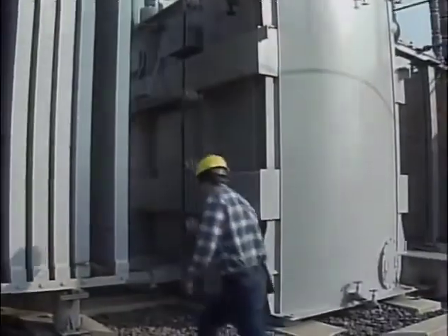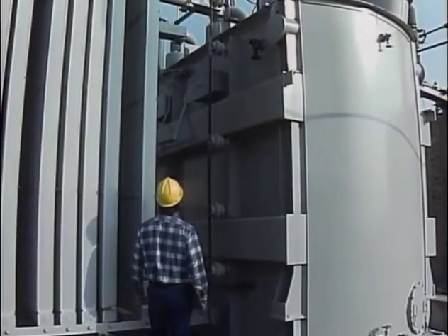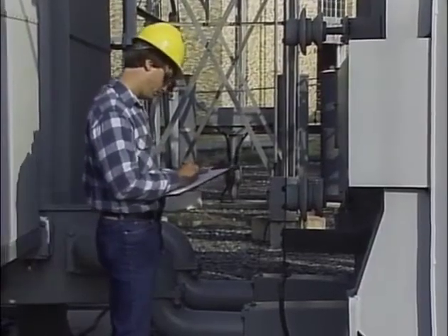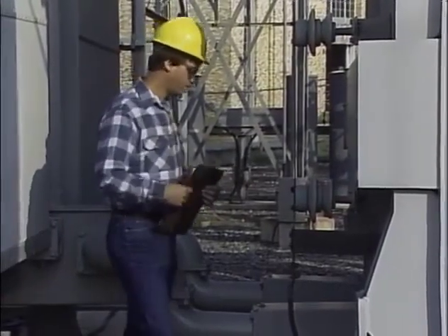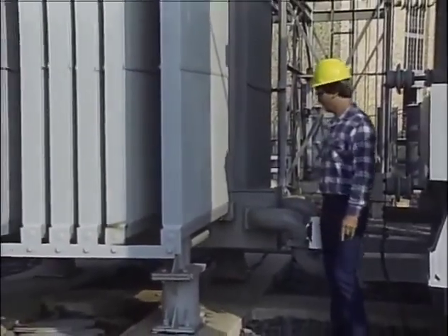The reactor grounds are inspected to ensure that there are no breaks or mechanical separations. The ground connections are checked to make sure that they have not corroded or worked loose. Corrosion or other signs of deterioration or damage should be noted for possible maintenance. Loose connections may be tightened on the spot.